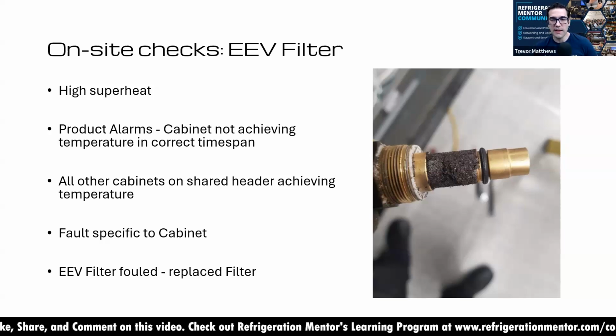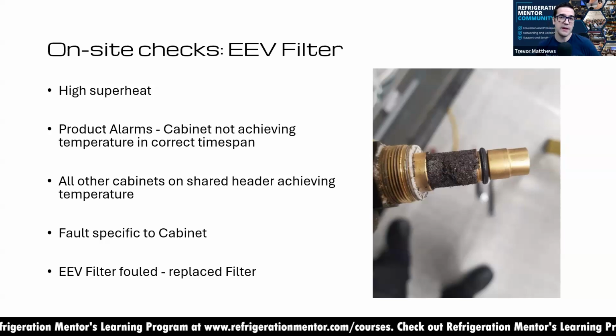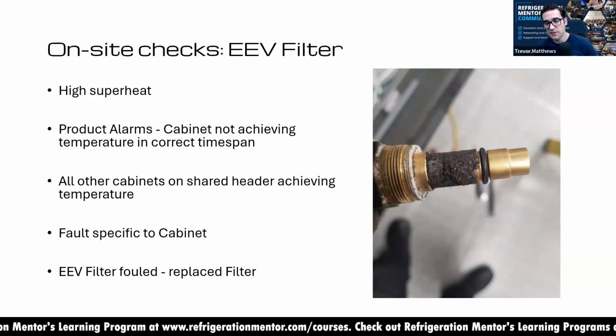You may not know that, like it may not be like what you're used to on a TX valve, where it's very noticeable. This one here is not noticeable. This is inside. You actually have to take the valve apart to look at it, pump down the circuit safely, pump all the refrigerant out, and then reclaim whatever's left in the lines to push it in.